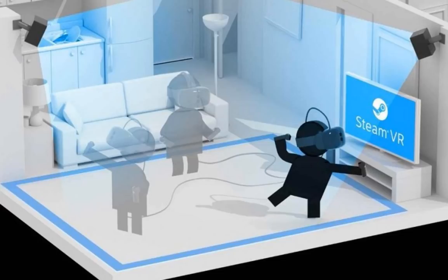to download and set up an application called Steam, which is a free application, and Steam essentially allows Chief Architect, Premiere, or Interiors to communicate with your virtual reality sensors and headset. And in Steam, you'll also map out your virtual reality space, so how big the room is and where the sensors are located in the room.